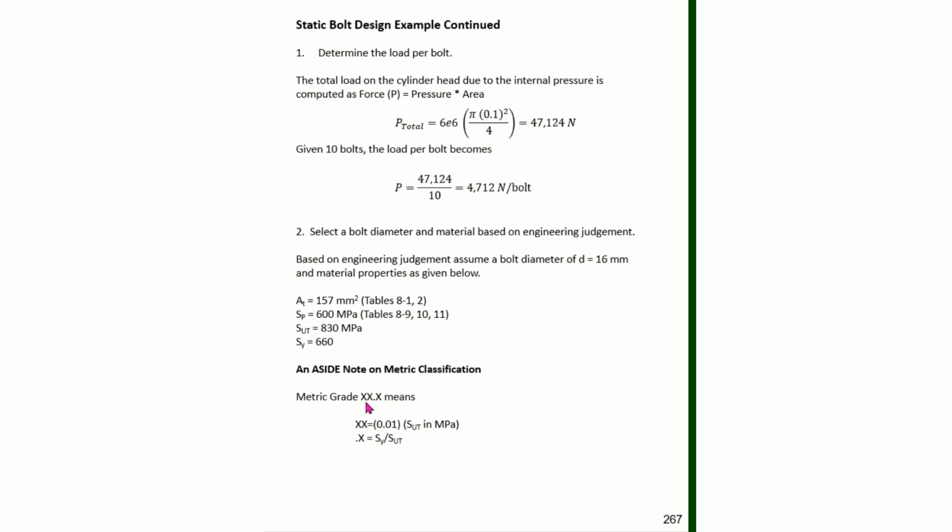So this is a great thing to remember, that you can actually compute the ultimate strength and the yield strength directly from the grade of the bolt, where you can't do that with the English classification.